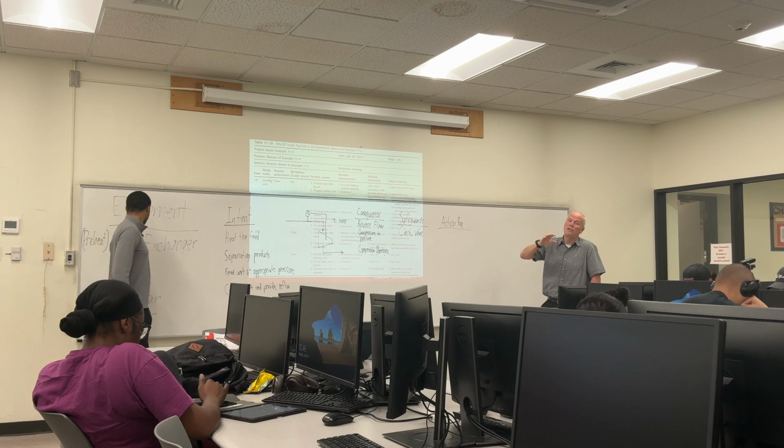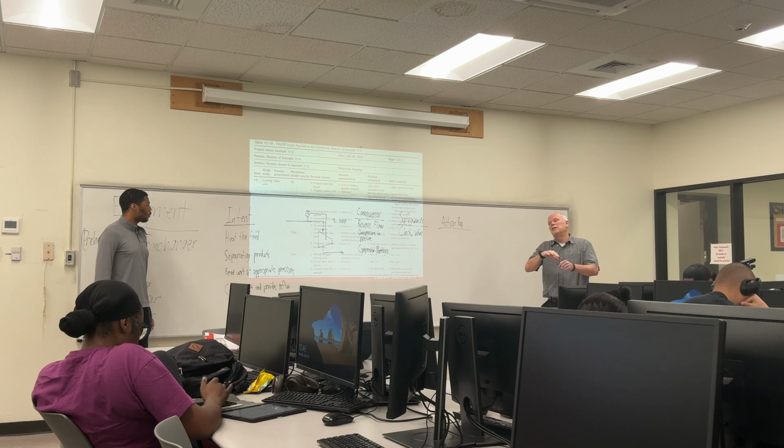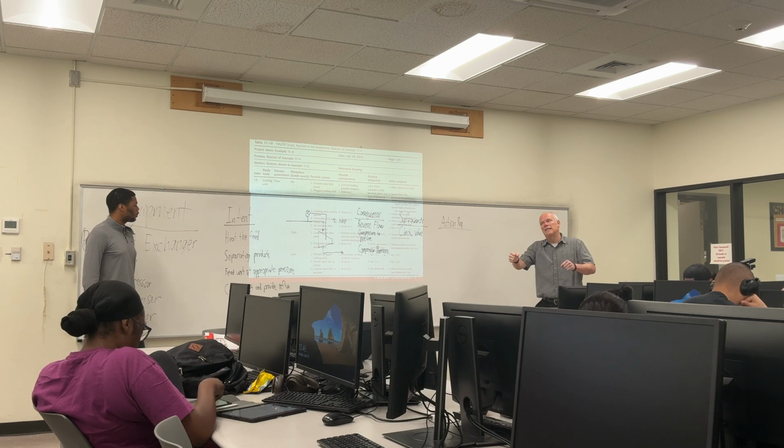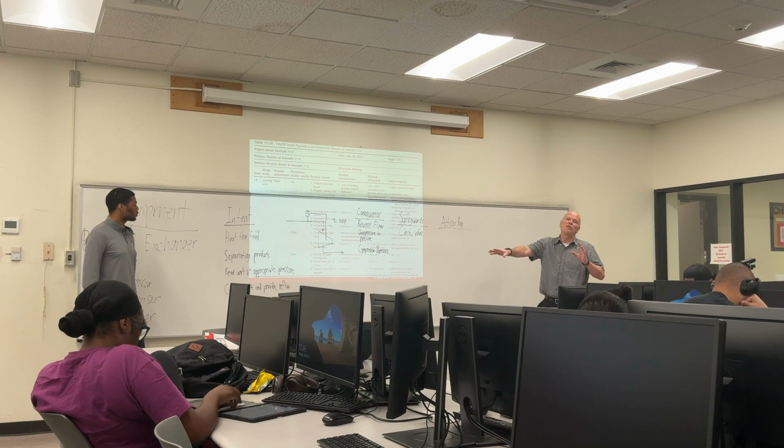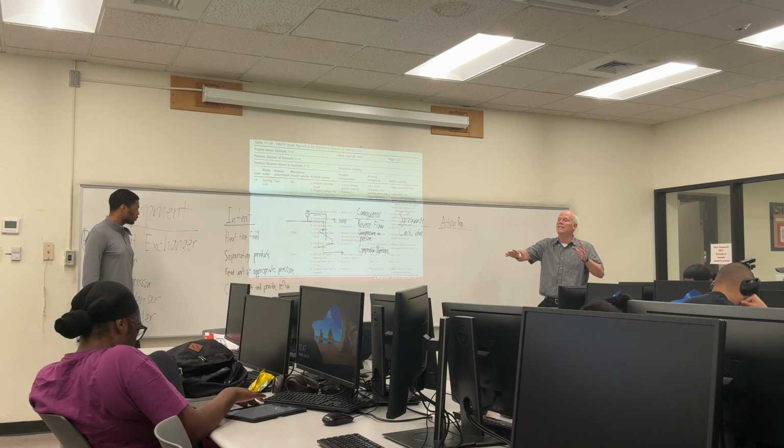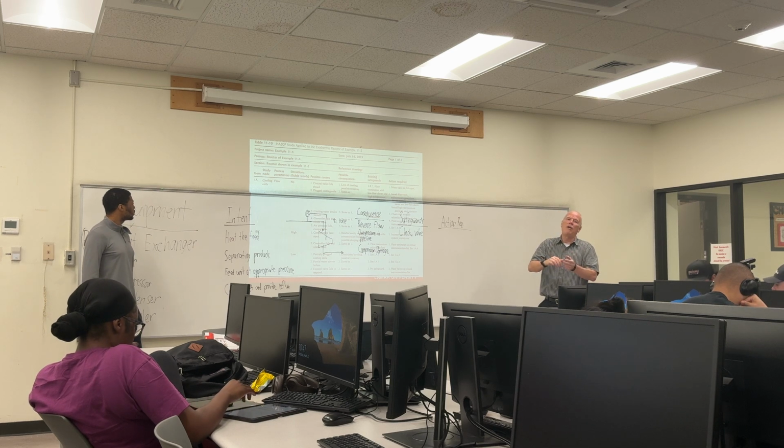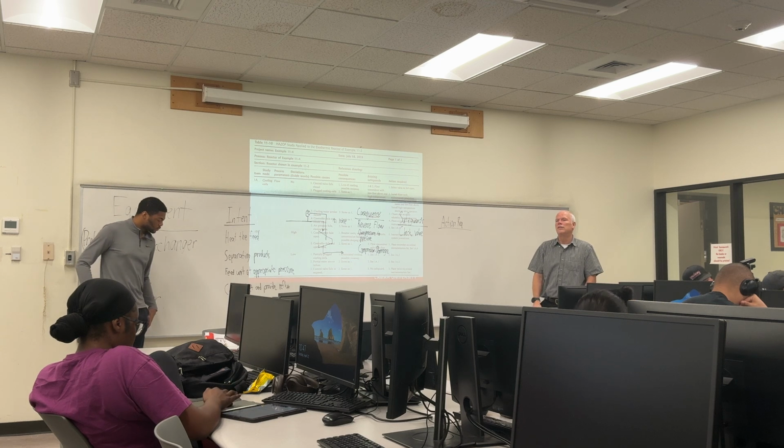There's a lot of different reasons why you can shut down a compressor. But once you shut one down, the logic gets met for the next thing and the next thing and the next thing. And so after just a very short period of time, within seconds, it's bam, bam, bam, bam, all the solenoid valves will drop, and you won't know what caused it, what shut it down, sometimes.